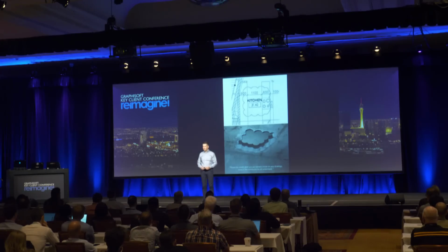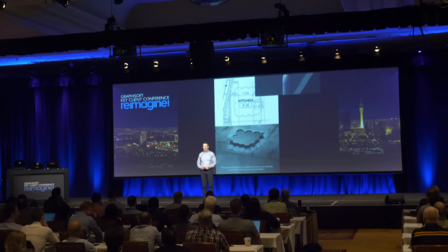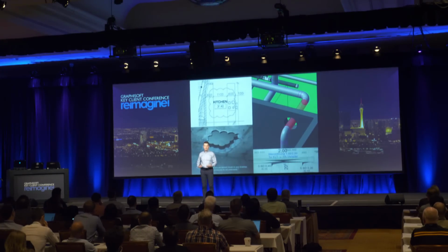So to avoid mistakes like a revision cloud cast in concrete, you have to provide BIM level information about the places of the holes. Solid element operation is not enough, because the clearance of these voids is bigger than the actual element, and also you need to have the proper documentation.